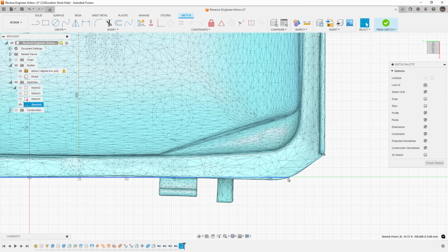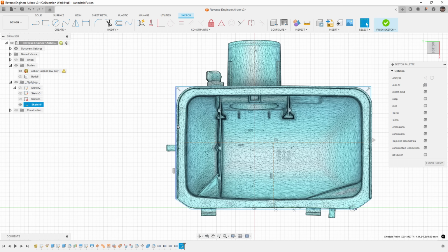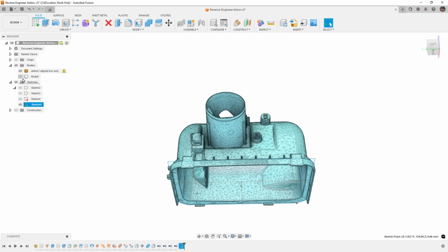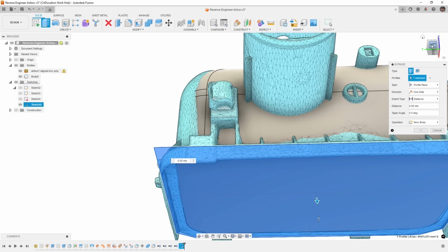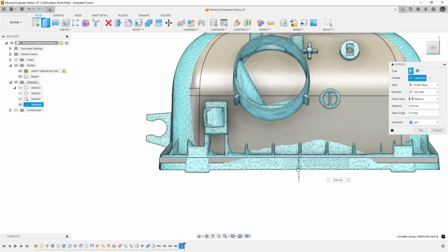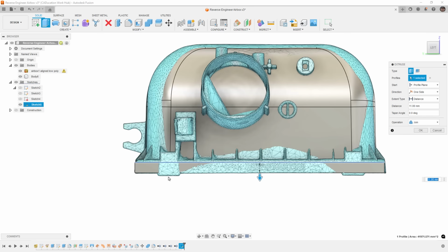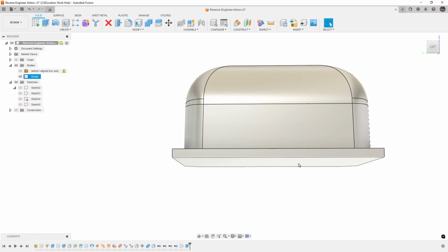So I'm going to bring this down. Bring this one down. We're going to have a fillet there and a fillet there, a fillet there, and it all looks pretty close. I'm not going to add any dimensions for this example, but hopefully you can go through that process if you want to. So let's extrude this. We are going to eyeball it down to, looks like maybe 11 or 12 millimeters. It's like 11.5. I'm just going to go with 11 for this. And we're going to join it to the original body here. So we're going to say okay.